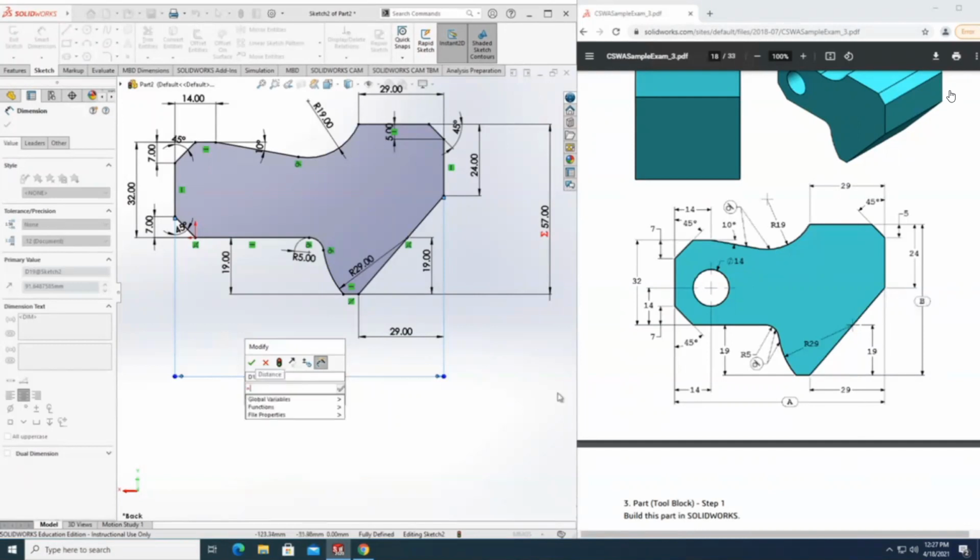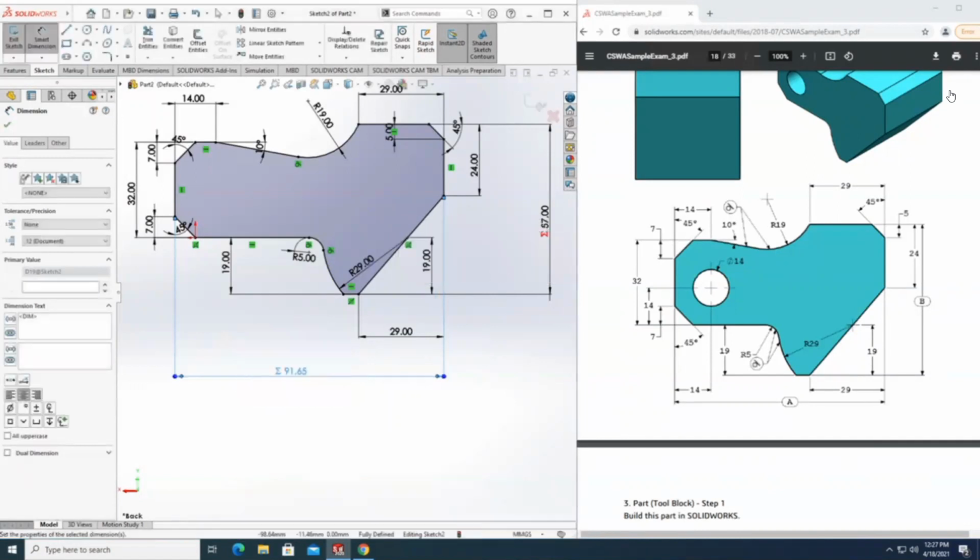So it's A equals to double quotes A and double quotes, and then you see that it gives you this symbol, which, if you hover over it, says create global variable. You click OK. It says this. Yes, we want to create it. And then we click OK dimension.